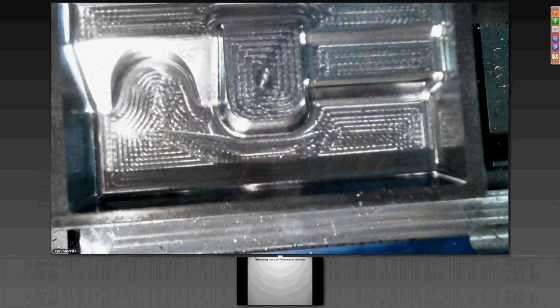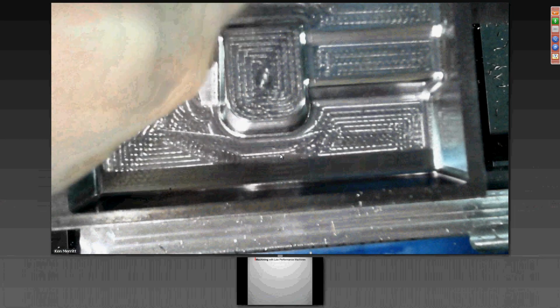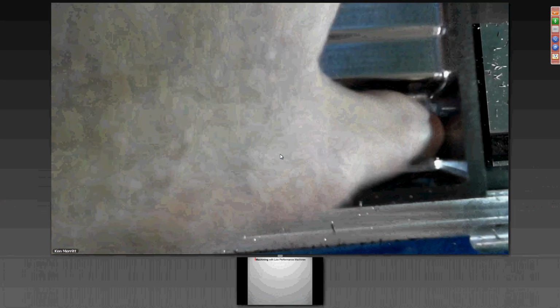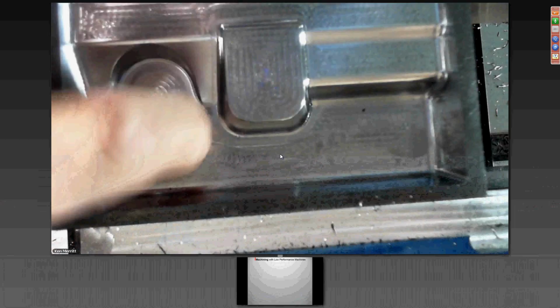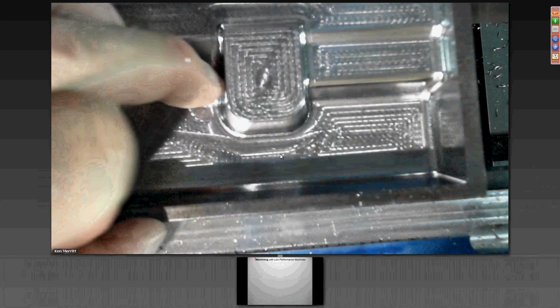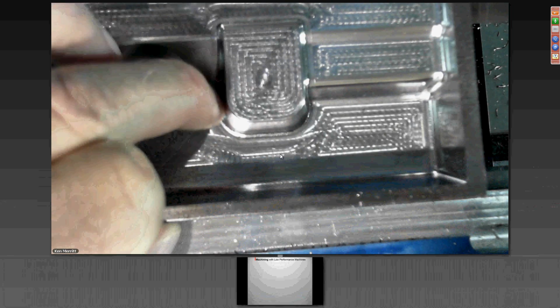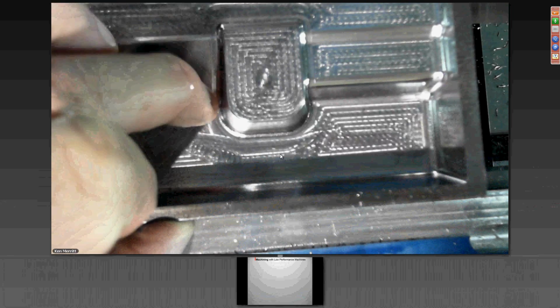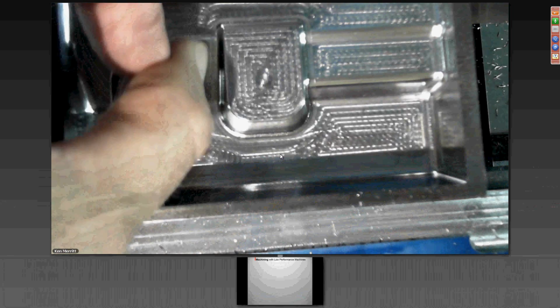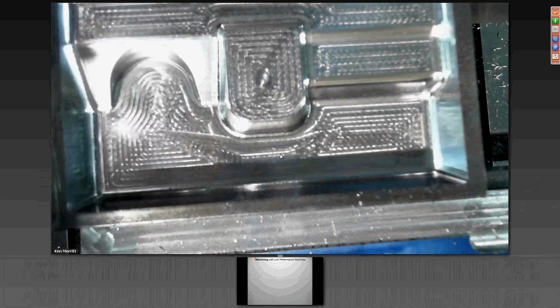And if I'm just doing kind of a thumbnail drag test along here, most of these walls I would say are easily within that 16 to 18 RA finish, especially these guys over here. They're really nice looking. The floor, easily 16 to 18. This area right here, I'm not really getting a scrape on the wall, not feeling a lot of vibration, so we're probably still 24 to 26 RA finish in that area.